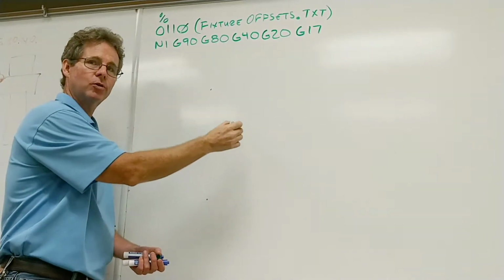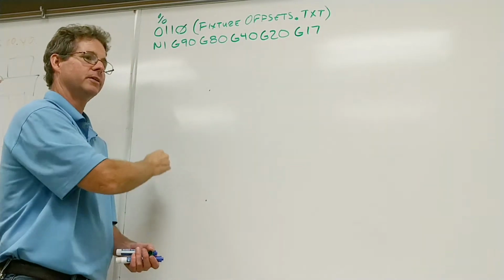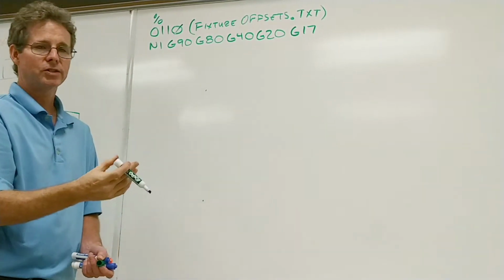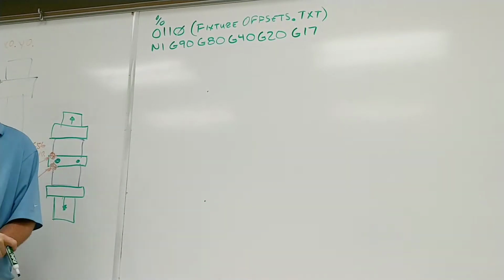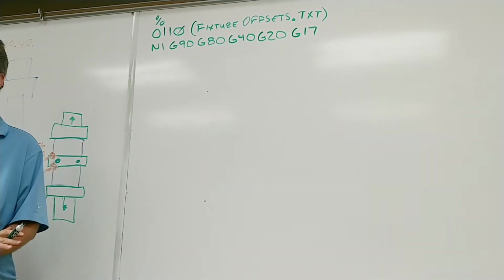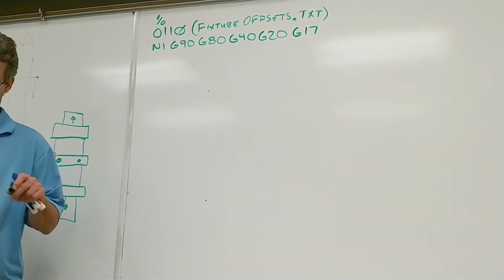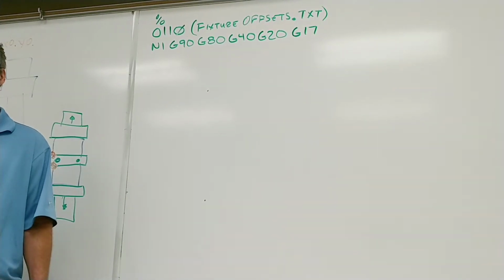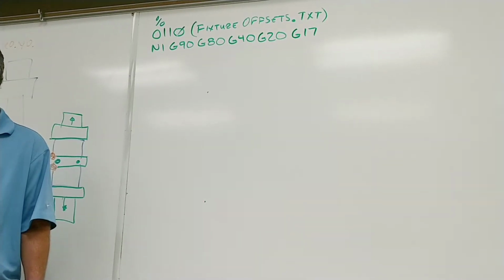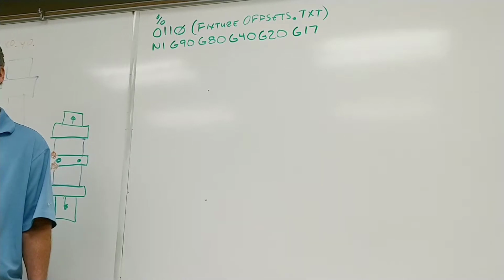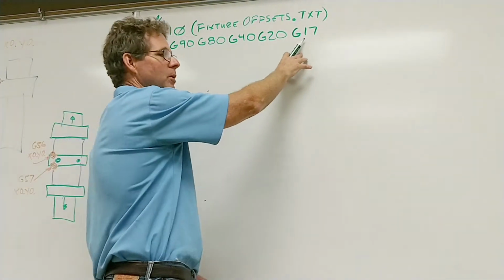You can do that in manual programming. People hardly ever do that anymore, versus doing an arc on the flat plane. With Mastercam, SurfCam, all your CAM systems out there, people rarely ever manually program and switch the work plane. It's hardly ever done. But if it is done, it totally jacks up the machine. If you accidentally have it set to G18 or G19, it's almost guaranteed that next time you press cycle start, you will crash. So this just guarantees that we are in the XY plane.